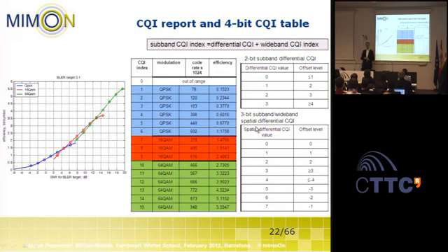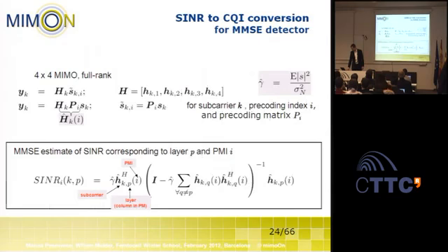There are also, in this reporting, of course, 4 bits that you need here to report these 16 values. There are also some more compressed schemes. Generally you need to report this based on a given bandwidth, so you need to generate several reports for each particular sub-band, but you sometimes also want to generate such SNR reports based on a larger bandwidth. To achieve this, you need to have some way to estimate the effective SNR on this bandwidth.